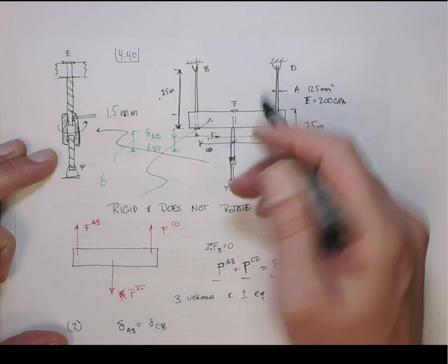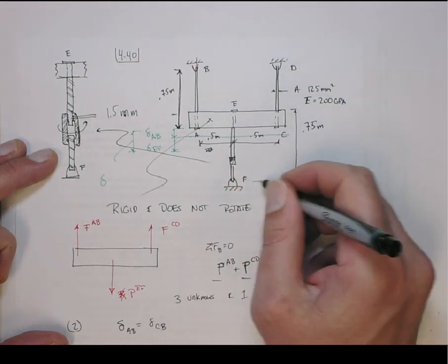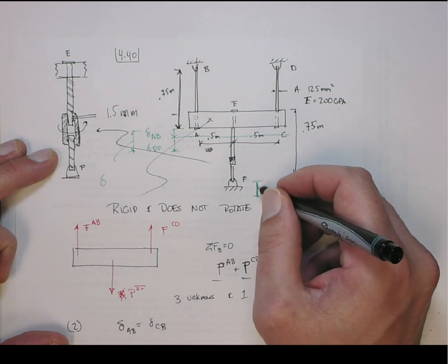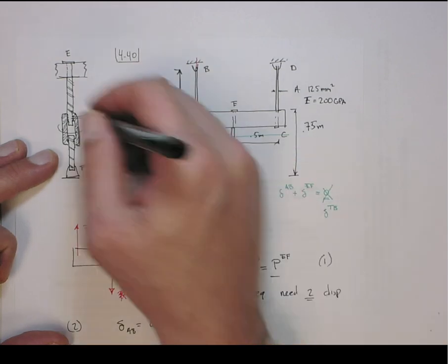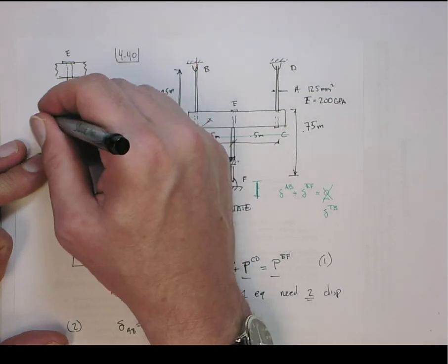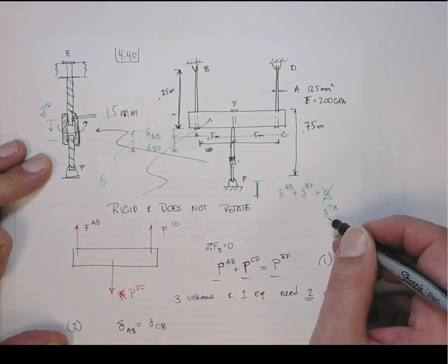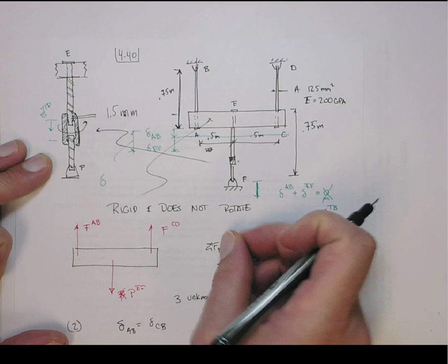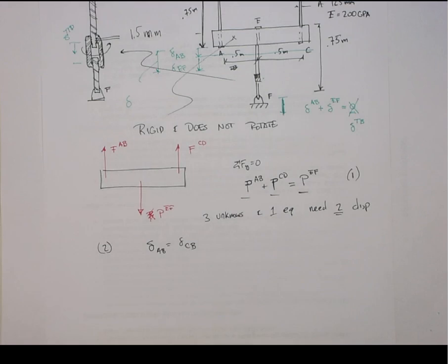If you imagine pulling this down at this point, that would be the amount that this would stretch. Now in this problem, you're not actually doing that, but this amount that the whole system has to elongate is the amount that's picked up in the turnbuckle. That's how close these two have to come together. That's the delta in the turnbuckle, okay? So actually this doesn't go to 0, but has to equal how much the threads come together in the turnbuckle. So it's the turnbuckle that's, in a sense, pulling this down. So that's the second compatibility equation. I hope I explained that well.